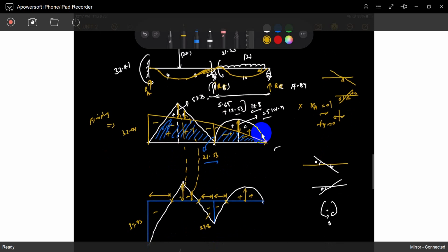So the deflection profile we can draw based on the points of curvature and the rotations. At A the rotation is 0, at B there is rotation. Based on that, you can draw the curvature diagram also. Curvature is 1 by R. Based on the deflection only we will get curvature. Curvatures and deflections, everything is interrelated. So that is the complete picture of the problem. Understood?